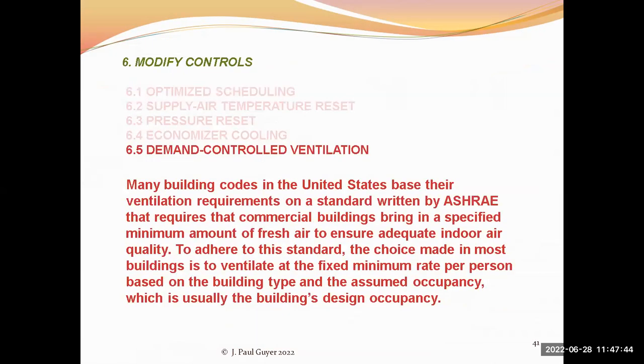Demand controlled ventilation. We've talked about this, that back in the old days, if you will, the quantities of outside air that were brought into the building for air quality purposes, for ventilation purposes, was determined more or less by rules of thumb. So many CFM per person in the occupied space, so many CFM per square foot of space, and so on and so forth.